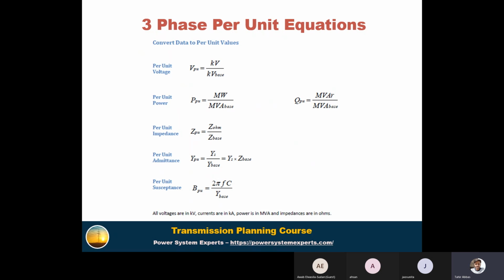These two quantities are more important, because at student level what students mostly do is simply divide by the megawatt base. Basically the three phase power, the MVA base, is also an S, so we divide by it. And if you need a proof, I can give you a simple proof. As we know, S is equal to P plus jQ. So S actual divided by S base; definitely we have to divide on both sides, so megawatt divided by MVA base.